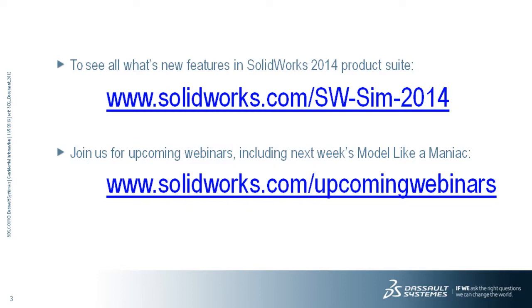Thanks, Delphine. There's a really quick question. Can SolidWorks Simulation be used to evaluate the deformation of polyurethane? That would be a nonlinear analysis, yes. Again, when you do performance testing on a product, very often you have either what's called linear or nonlinear materials. To make it simple, linear materials are materials such as steel, aluminum, and nonlinear materials are materials such as plastic, elastomer, rubber, that kind of material. So yes, we can do that in what we call a nonlinear analysis.